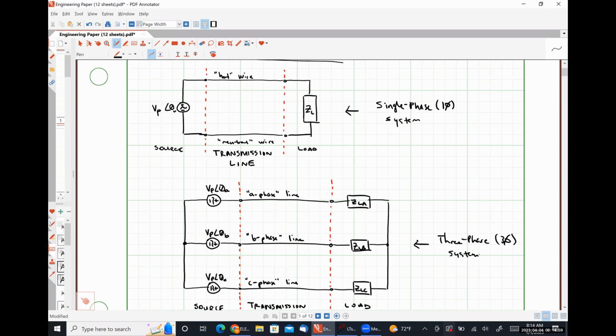We get a DC component with a sinusoidal oscillation superimposed on top of it, which means the power is sinusoidally oscillating as well. So the amount of power that anything plugged into a receptacle is receiving isn't a constant value. It is going up and down around some DC operating point, and that DC operating point is the average power.